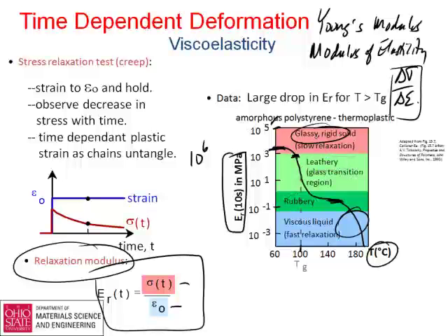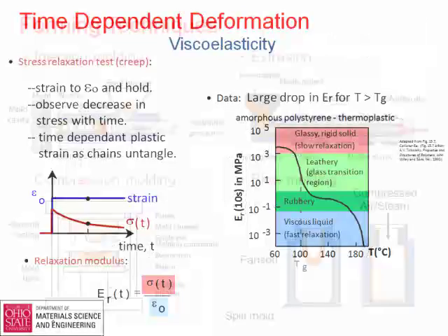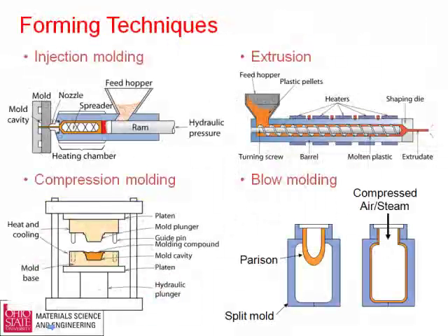So at really low temperatures, it could feel almost like a piece of window glass. Get it to a high enough temperature, and it's like hot honey. And that's pretty much for similar sorts of reasons. Basically what you're doing is you're able to break those secondary bonds thermally very easily, is basically what's going on. So we can use these properties.